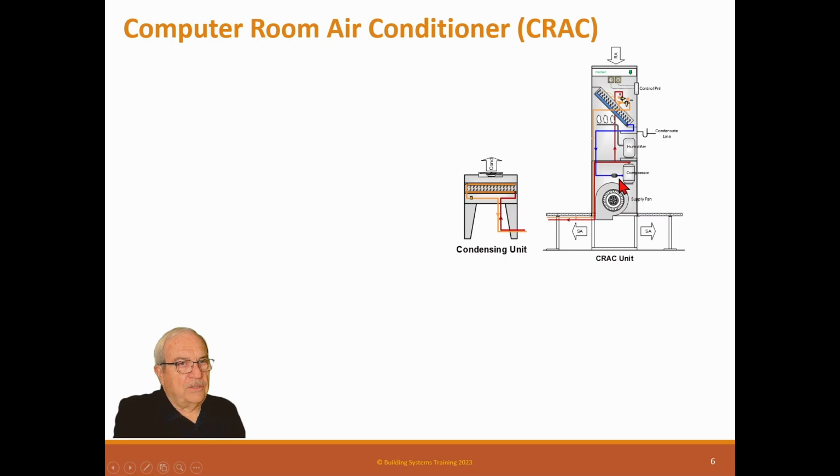space to prevent static electricity from sparking. If you have magnetic media, and you spark it with your finger, you can destroy the data that's on the media. So it's really important. They keep the humidity level slightly higher in these spaces. The way these work, this is a self-contained unit. It has a supply fan. The supply fan draws the air down from the space through the cooling coil, through a chamber, to a humidity chamber, and out, and blows it underneath the floor.